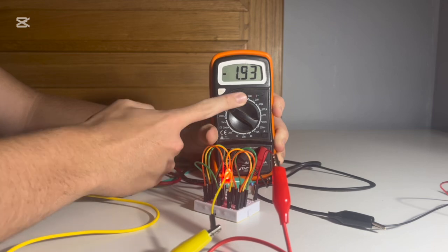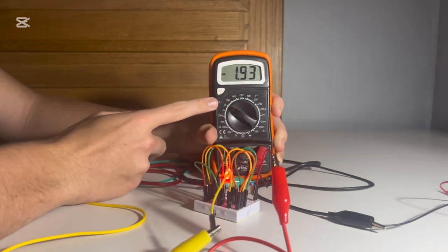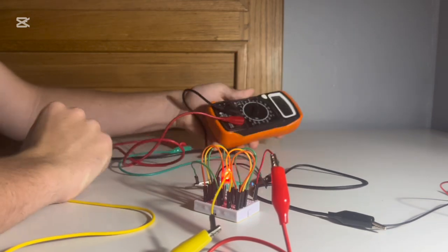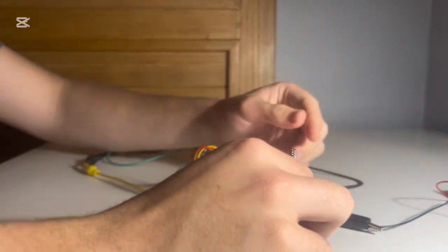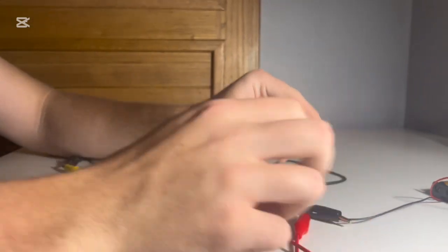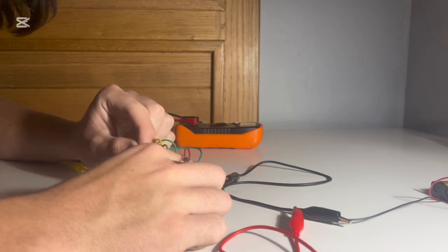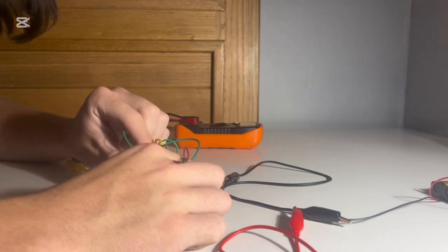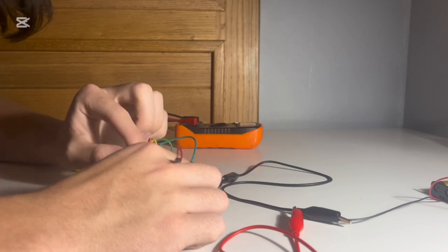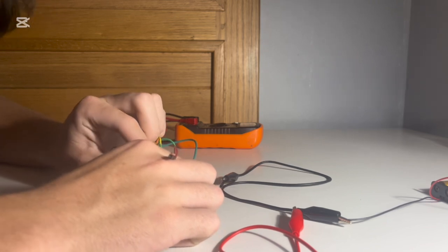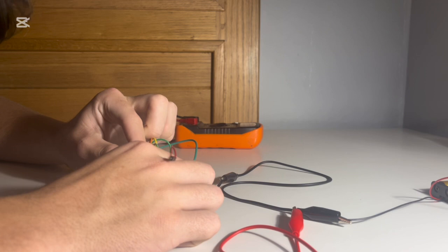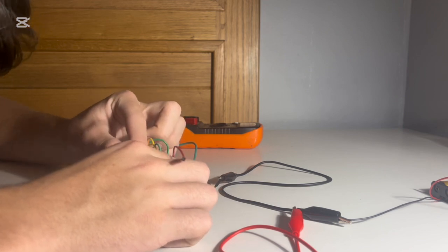If we look at the voltmeter to read the volt drop across the LED, we will see that it is 1.9 volts. Our voltmeter is set to a maximum rating of 10 volts. Now we will disconnect the voltmeter to sit in parallel with the second branch of the circuit containing the second LED. We can see that the volt drop across the second LED in the second parallel branch is also 1.9 volts.